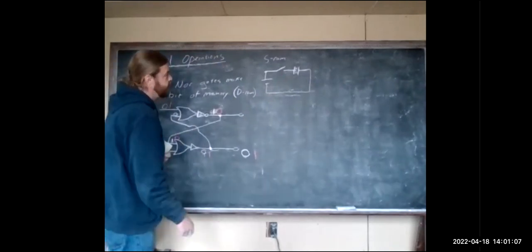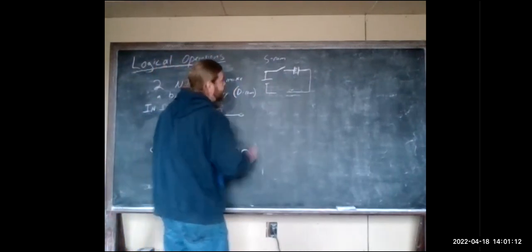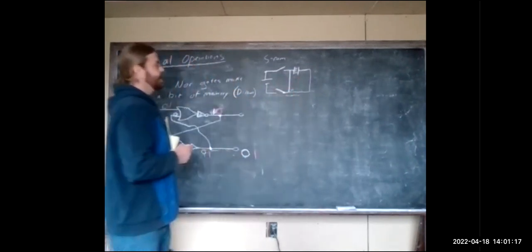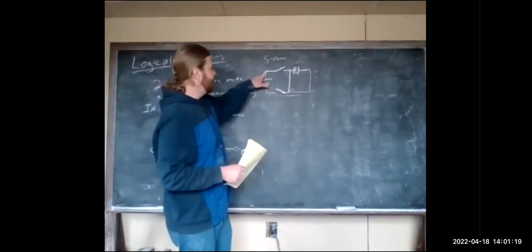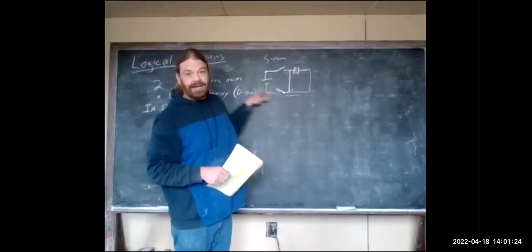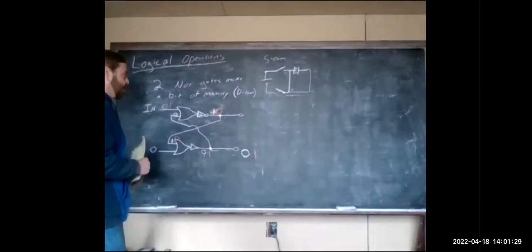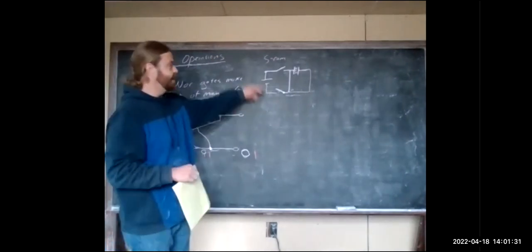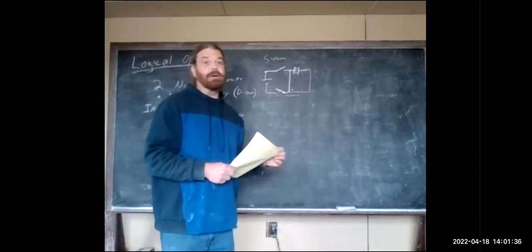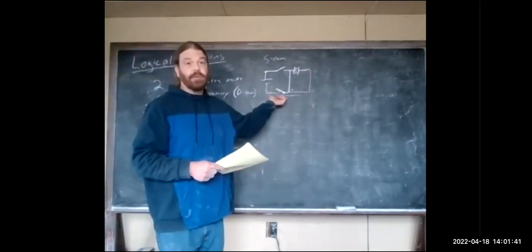Or it's actually an isolated thing. It actually looks more like that. So we have 2 switches. If we want to put something there, we close this side and fill it up. If we want to take it out, we close this side and let it drain back to ground really quickly to get our 1 or 0. So less pieces, so easier to make, cheaper, but more temporary. This one will last as long as power is supplied, and this one will fade away.